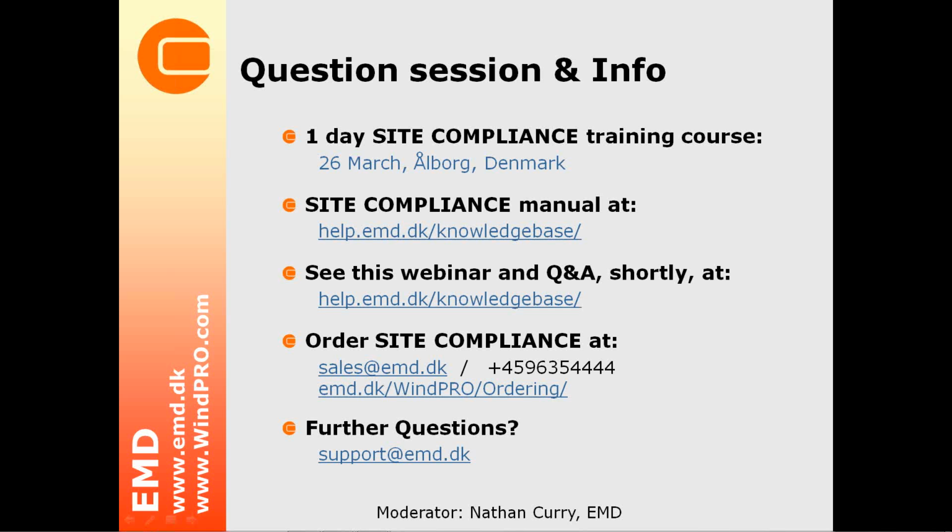There's a question here that relates to that in my calculation I had some green checks and I had some yellow checks. The question is saying that I changed the IC class to a class 2B, but I still had a yellow flag for the effective turbulence calculation. And how can I conclude that the class 2B turbine is a good choice since the turbulence is exceeded? Well, it's also an approximation, you could say.